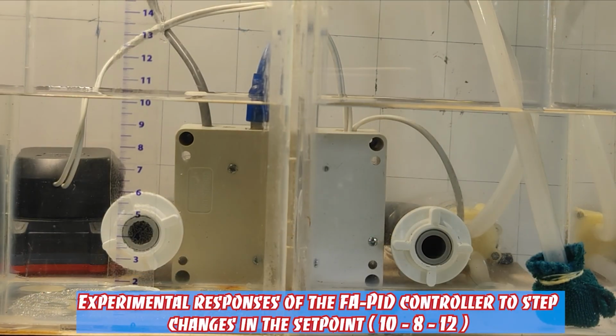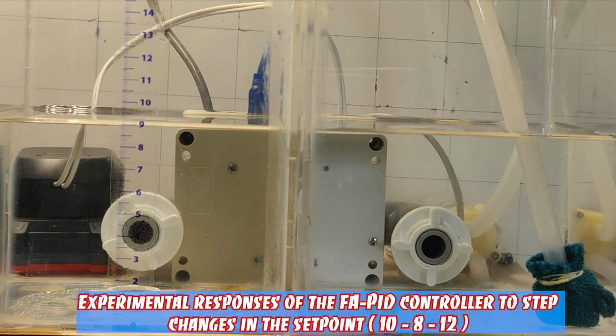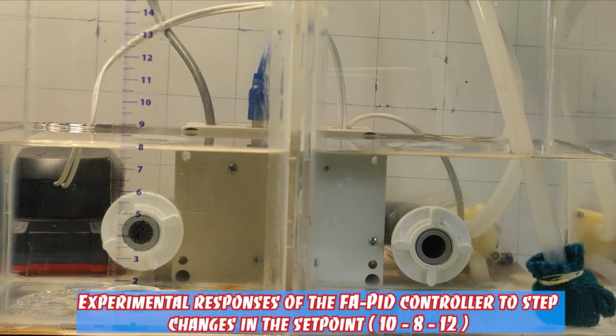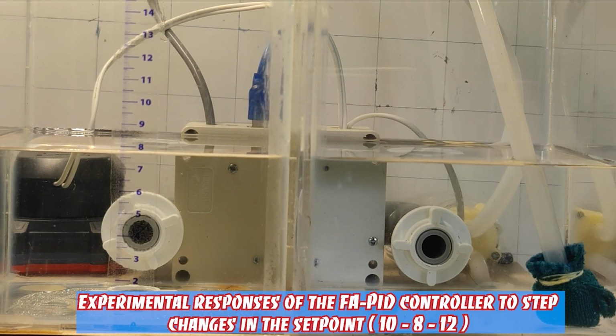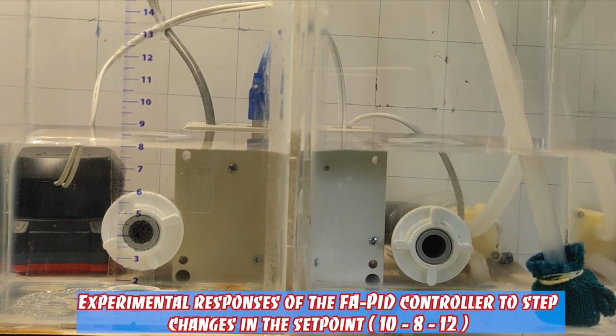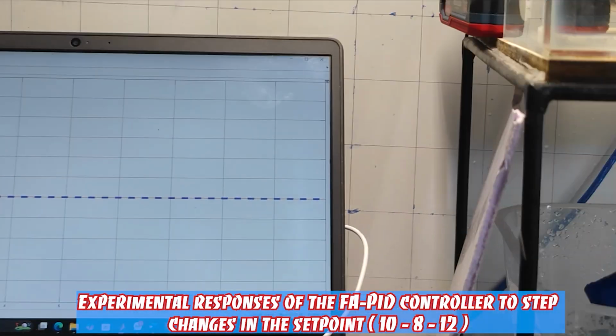This time, I did not change the valve positions, but instead varied the reference signal from 10 centimeters down to 8 centimeters, and then from 8 centimeters up to 12 centimeters. Due to the system's nonlinearity and signal delay, overshoot and oscillations appeared during the reference transitions. However, the system quickly stabilized and showed excellent tracking performance. Once the steady state was reached, the response remained stable with almost no oscillation.